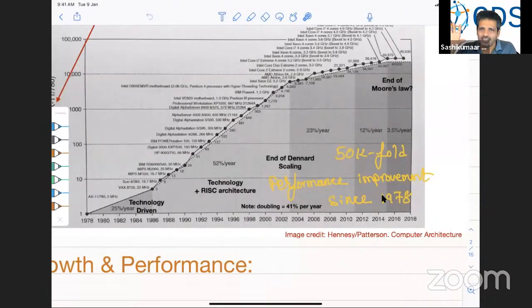Usually in the 90s and 70s, an SMPS was 250 watts, or even 350 watts, I think, at maximum. But nowadays, if you attach any GPU card, even a very basic GPU card, then 250 or 350 watt SMPS units are not enough. You probably have to go to 650 or 750, depending on the card that you are adding. So it's not only about the power consumption of the processor. In order to support the increased power requirement of the processors, the cooling system also raises a lot of complications. So this era is a bit of a complex period.